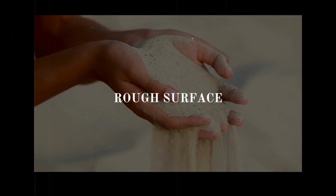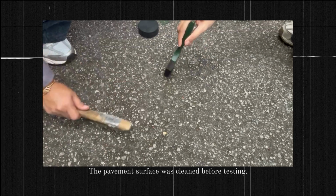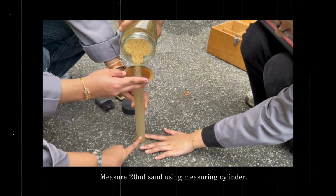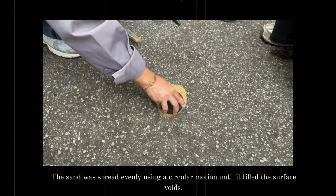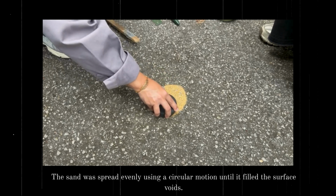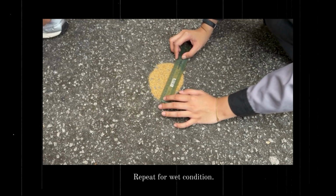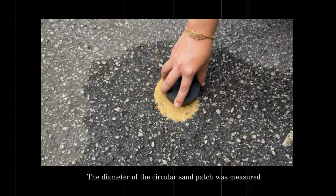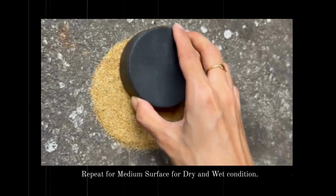Rough surface. The pavement surface was cleaned before testing. Measure 20 ml of sand using a measuring cylinder. The 20 ml of sand was poured onto the pavement surface. The sand was spread evenly using a circular motion until it filled the surface voids. Repeat for wet condition. The diameter of the circular sand patch was measured. Medium surface. Repeat for the medium surface in dry and wet conditions.